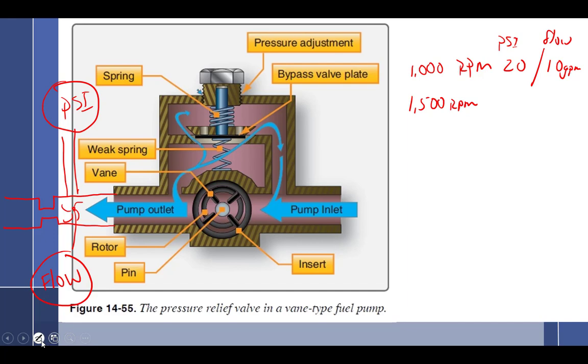Okay, that's the same issue. What exactly was all of that conversation about? 20 PSI. What does this do right here? It's a release. If it's 21, it relieves it. It's a pressure relief, and I've set it for how many PSI? 20. Okay, so this is where I lose people. It's set for 20 PSI.